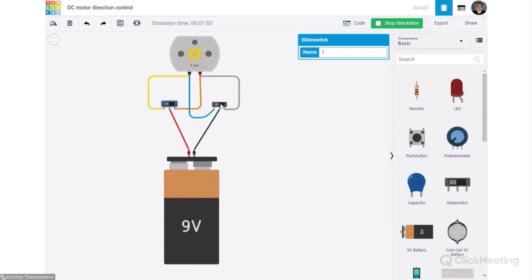We stop, and then it's counterclockwise. I just connect the common terminals with positive and negative, and then the others I connect terminal 1 and terminal 2 to the two terminals of the motor.